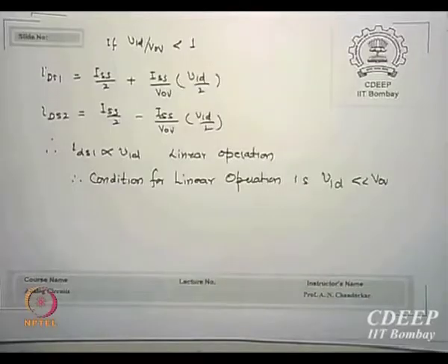See, the total AC currents are much smaller compared to DC currents. That is what I keep on telling, that the variation there is small enough to neglect. The net current will be only the DC current. Is that clear to you? Because the average value is 1 plus 1 minus, the average is 0, and the net current at any given average time is only ISS. Is that correct? This is the way it is calculated. Instantaneous current is ISS plus small i, but average current is always ISS.